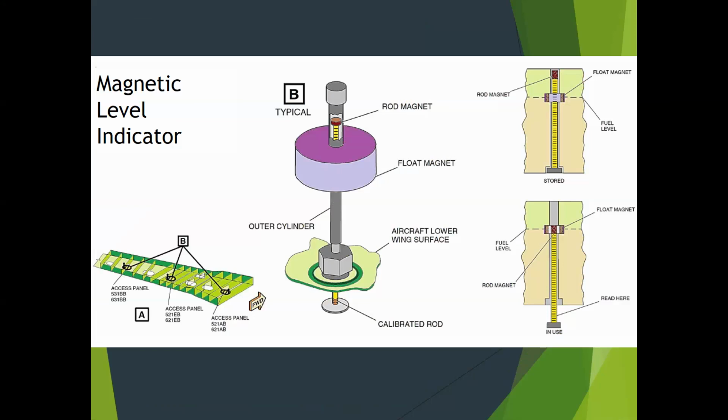Is the level of the fuel always at the top of the rod? These are skinny fiberglass rods, and then you've got this big float right here. What would happen to the rod if there was a big weight on the end of it? It'd constantly be sitting there going like this inside the tank, right? So having that float down keeps it so that it's not bending that rod back and forth all the time. So we pull it down till it hits the top of the fuel, we can feel it,